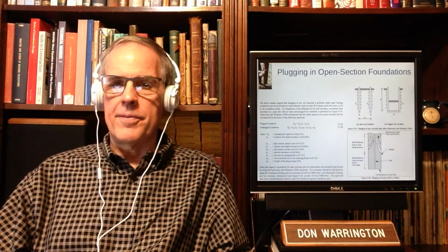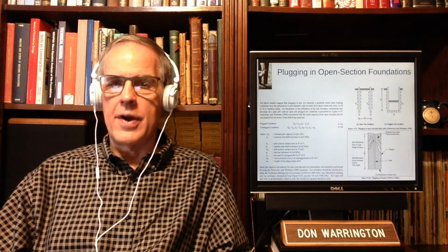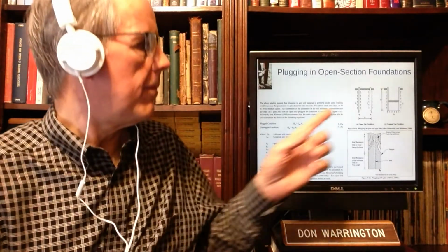Plugging is something which is only now, in the last 10 or 20 years, really getting quantified the way it should. With an open-ended pipe pile, if you drive it, you have an issue of whether or not the plug in the middle of it is going to go down with it.